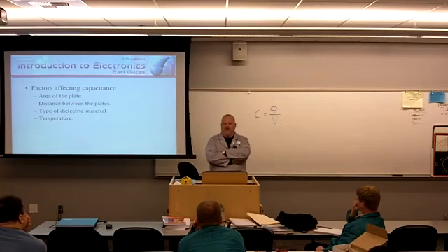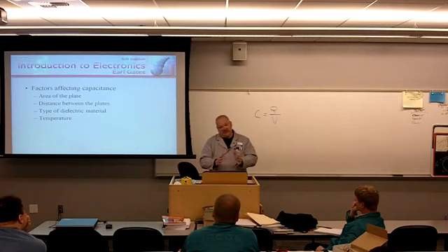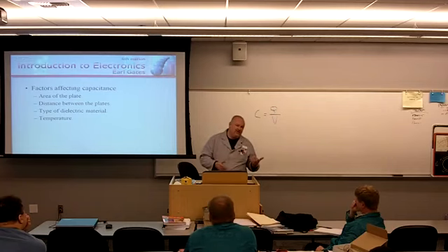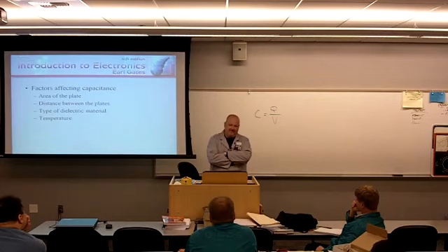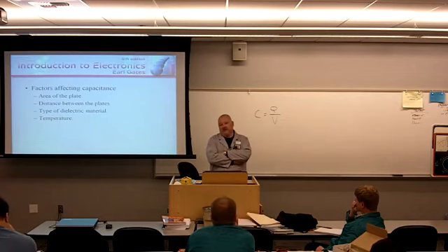Capacitors are going to expand and contract. So as the plates expand, it can hold or affect Q. As the distance between the two changes, it's going to affect V. So the bottom line is the amount of capacitance will vary with temperature. For some circuits, like at room temperature, it's not that big of a deal. For some stuff, I don't think in your wildest imagination you've ever really thought it through where a lot of electronic systems are used. I mean, it's a pretty harsh environment.